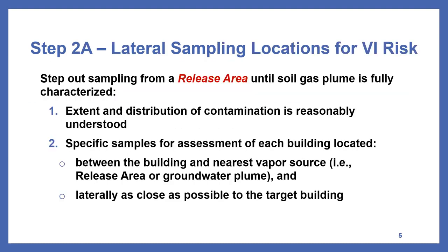For Step 2A, the distribution of shallow soil gas contamination should be evaluated. The objective is to evaluate the nature, distribution, and extent of shallow soil gas contamination, both laterally and vertically, and use that information to evaluate vapor intrusion risk to building occupants.